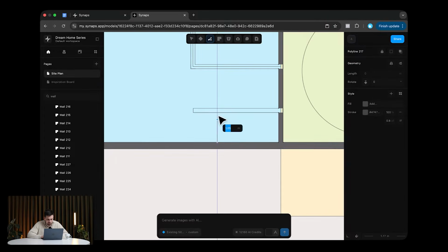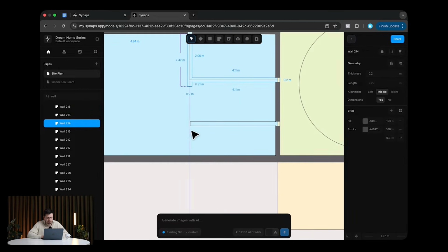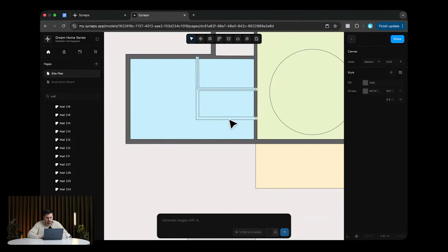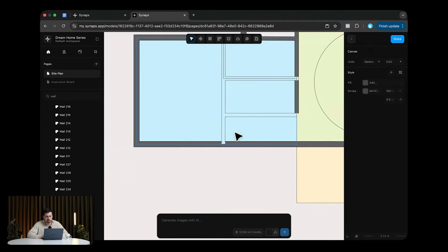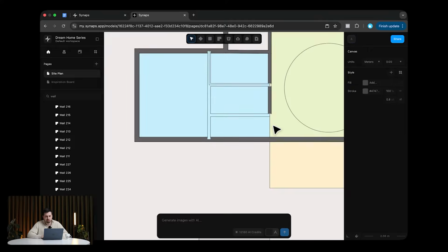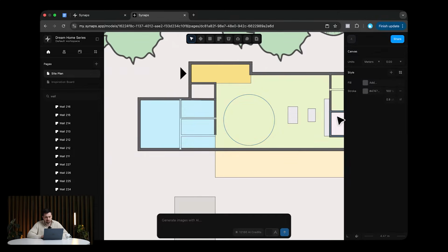I think 1.2 meters here will be more than good enough, so we'll be fine in terms of distance there for circulation room. We'll extend this up to here, and then this wall, I'll probably bring it right here. Now, the reason why I'm leaving the entrance to the room here instead of here is because there is an extra level of privacy when someone is getting out or inside the bedroom. So it's not directly visible from a lot of angles of the interior, right?